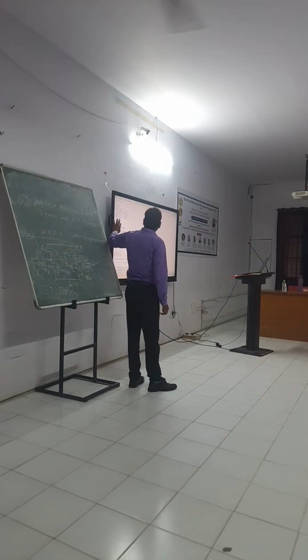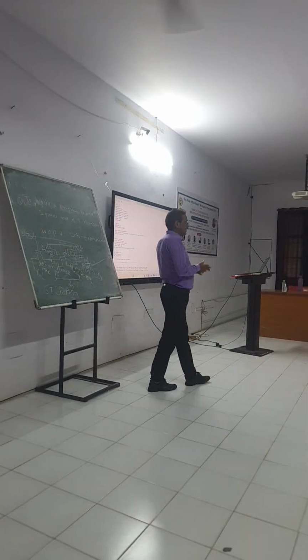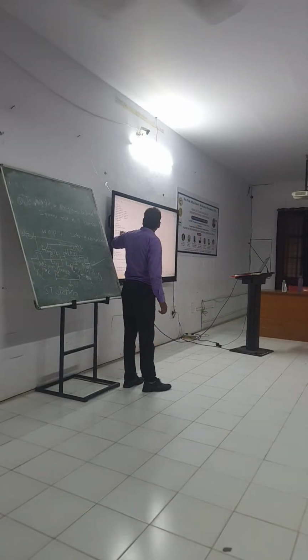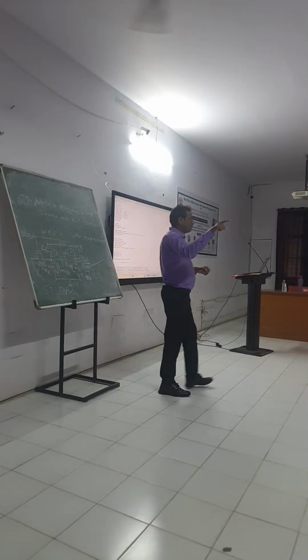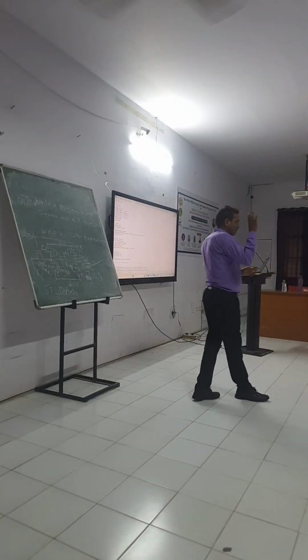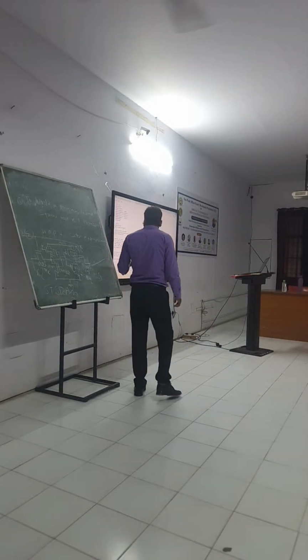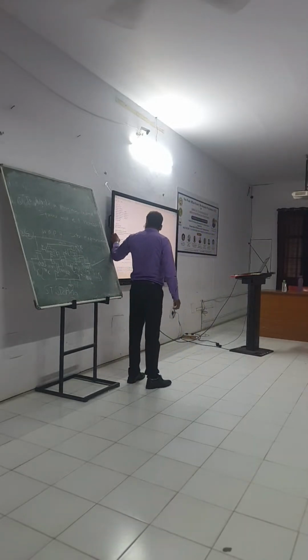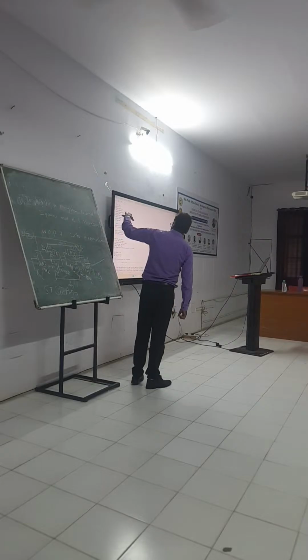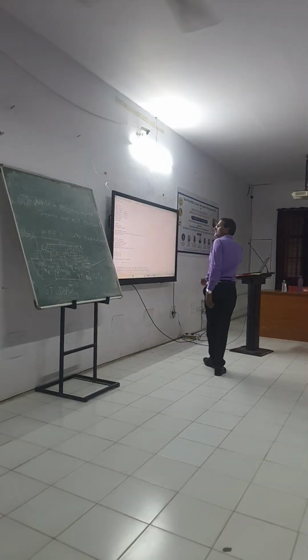Global VDD means ground and VDD are global type; we have to define them. Then the dot param time step: we have to define the clock, rise time, fall time, and duration. That we have to define. Then this is the library.